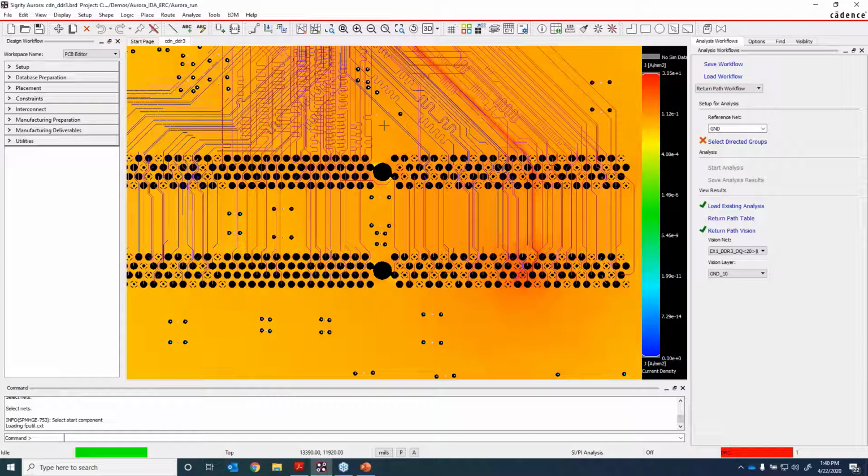Great, thank you. So what is coupling coefficient 2%? What if we increase or decrease this value? It marks the threshold of coupling that it reports. Setting it at 2% means any traces that have coupling coefficients at 2% or higher are what's going to be reported. Anything below that is just ignored.